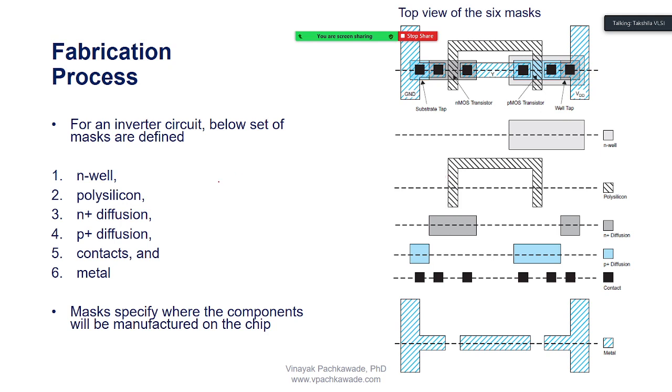So what I do is that I have two NMOS transistors here, A and B. This is ground, and then I have a PMOS about here, A, and then another transistor B, and that's VDD, right? And then here is the output of this logic, and I want to draw the layout. So first, for my sake, I will define the terminals, drain and source. This is drain and source, this is source, drain, source and drain. And just for simplicity, I am not drawing the body connections.